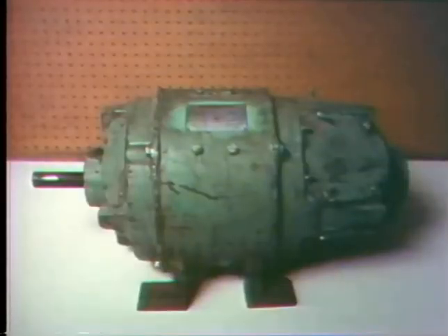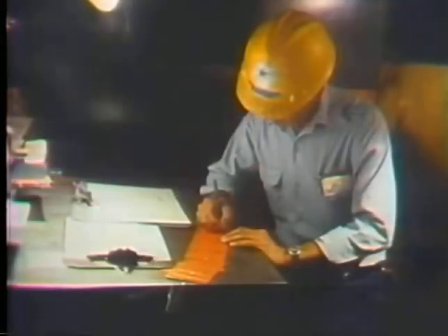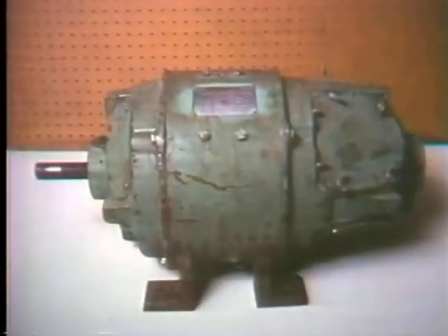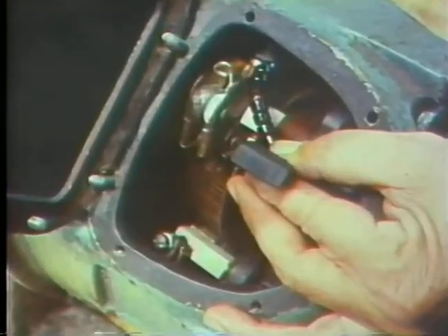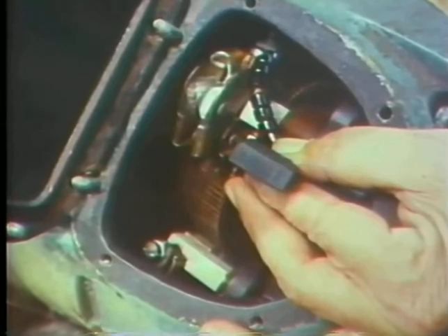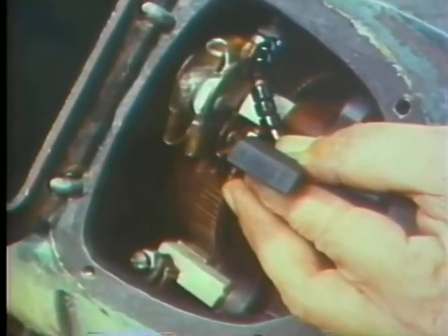We have this motor in the shop, and we'll use it to demonstrate good maintenance practices. If you are to make repairs in place, you must follow the plant's tag-out procedures and verify electrical isolation before you start work. This is a compound DC motor. We'll mention the kinds of problems you'll be running across first, and then go on to cover what you can do about them. Let's start with the commonest source of trouble, and the one that's easiest to correct: the brush.